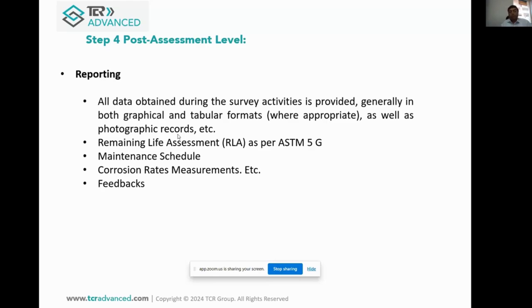It would be like my design would be for 10% coating defect or 50% coating failure. So with this type of survey, when you find a coating defect, you repair it so that your coating integrity will come back to its original state, and you can attain your design life, and thus you can increase the design life of your system.